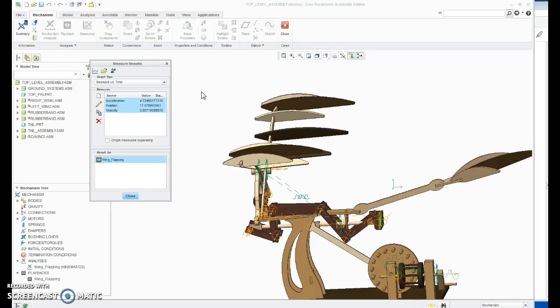So, funny enough, if you actually notice in the video, I had predetermined values in there beforehand, and what that means is I actually didn't erase the not displayed. Oops. So this is a perfect example of why, when you close an item, you want to erase it, because you can get errors down the line that you may not be able to understand. So what I did was I actually closed out the entire thing, erased the not displayed features, and then reopened, and then did the exact same process to get all these values so you can create your data. So another very important thing, why I keep stressing it, is you need to delete everything when you close something.